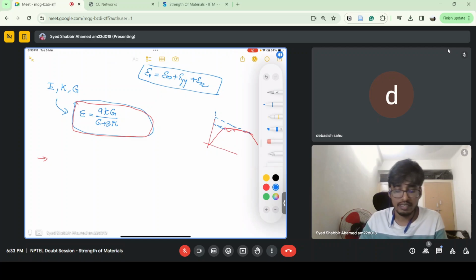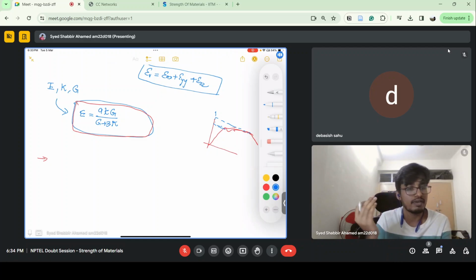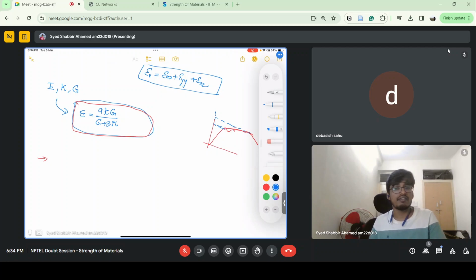Rectangular cross section is also there, but generally it is preferred that we take rounded bars, or a circular cross section bar, because there is no concentration of stress at endpoints. When you take a circular bar or different things, there might be some changes here and there.